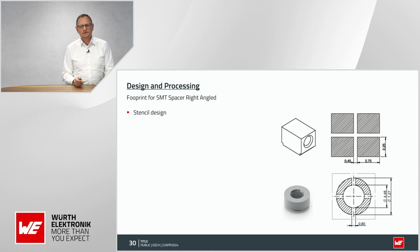So one point here is about the stencil design. We've been talking about that previously. And now here the pattern field, of course, is the fields for the solder paste. But there are big corridors here inside. And those corridors are really important. You can't make it one surface.